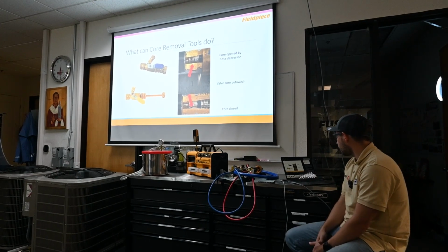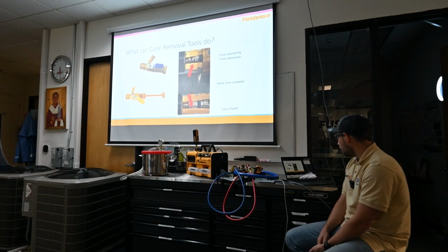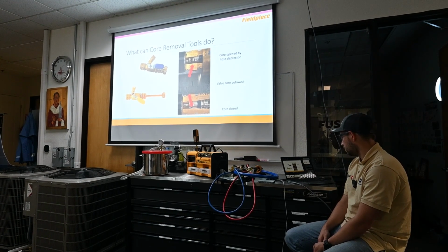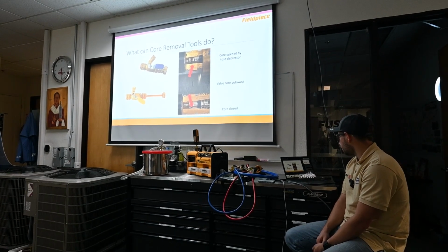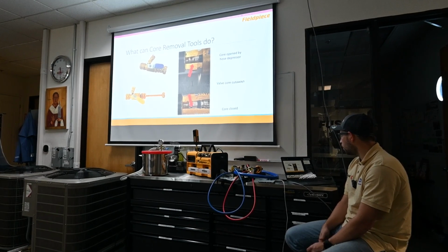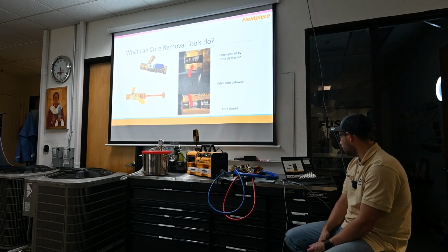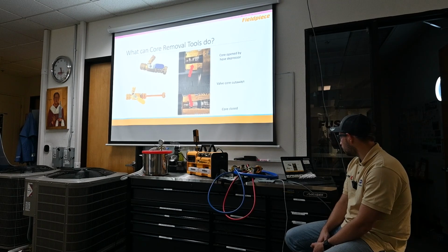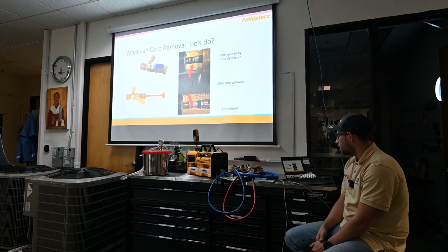The side port has a valve core installed and is connected to the system when the ball valve is closed. It should be rated for vacuum, with a quarter turn valve for fast operation, useful on a manually operated service valve to eliminate stem leaks when doing service.